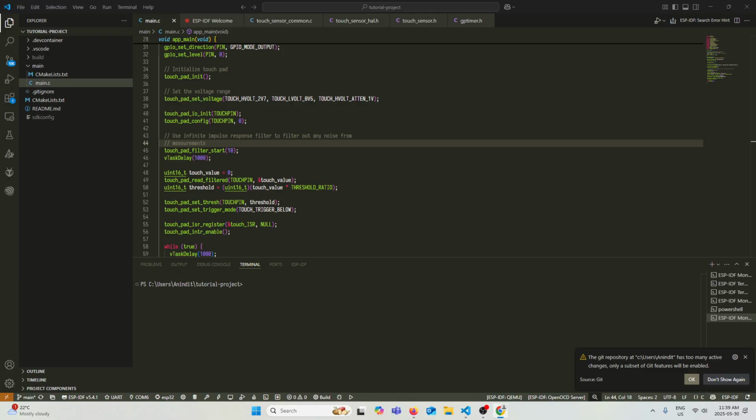Binary starts counting at 0, but ADCs are most commonly 10, 12, 16, or 24 bit. Looking at the waveform of an analog to digital signal, an analog signal would have a smooth, continuous slope representing how the signal can be infinite values between 0 volts and the maximum voltage. The waveform of a digital signal changes in steps, with a finite number of steps equal to the ADC's resolution, divided evenly between 0 volts and the maximum voltage. The signal change at each step goes low to high or high to low.